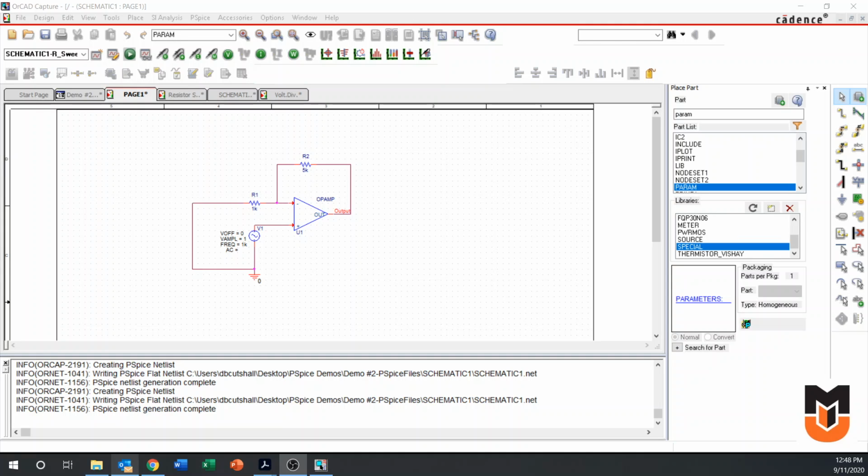One other thing that I want to discuss about Lab 2 is how we're going to create our input voltage. In your simulation, and what we'll see in the lab, remember, we're going to need a negative and a positive power supply to power our op amp. So in your simulation, you'll have negative and positive power supply connections on either side there. But we also need some type of input voltage that's being input to either our inverting or non-inverting terminal.